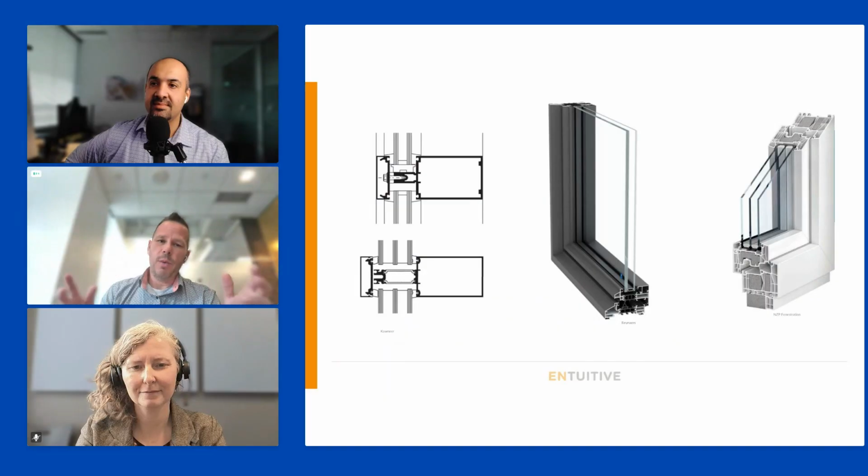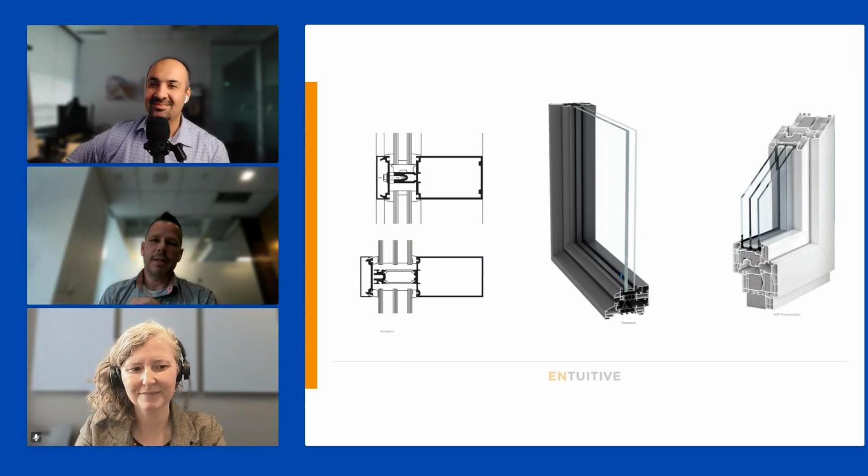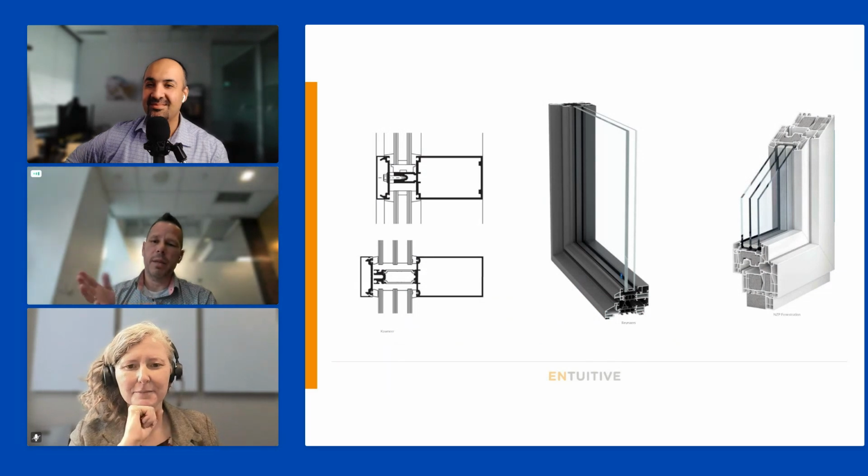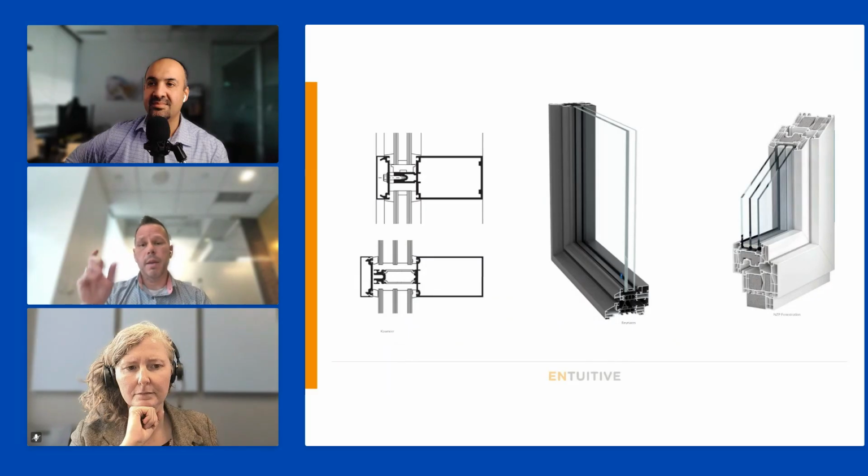You have to put this window, this piece of glass, into a frame. In most cases, I mean, sometimes we do structural glass with no framing at all, and that's really great, but not in most buildings. So here's a couple of examples, starting at the left, a traditional curtain wall system. The top one has almost no thermal break, maybe about a 6 millimeter thermal break just on the nosing of the screw spline there. The other one has a fairly beefy thermal break, enough to accommodate triple glazing. You can get a beefy thermal break like that, probably about 25 millimeters deep at least, maybe a bit more, without having to go to triple glazing, but it just depends on the frame design.